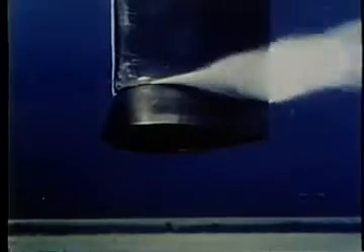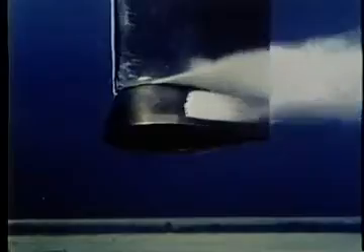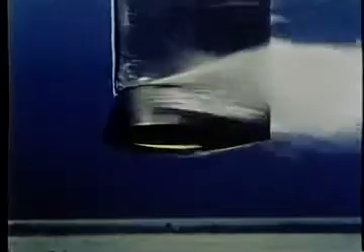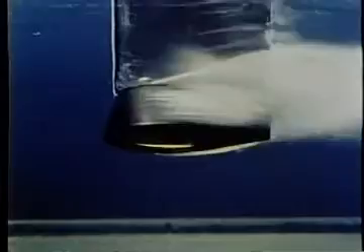At low speed, cavitation on the foil itself first occurs in the low-pressure core of the laminar boundary layer separation region associated with low Reynolds number. At higher speed, and thus larger Reynolds number, the appearance of the cavitational flow changes. Transition from laminar to turbulent boundary layer has occurred. Laminar separation has been suppressed, and cavitation now begins near the minimum pressure point, close to the leading edge.